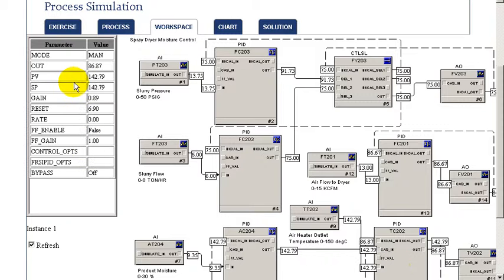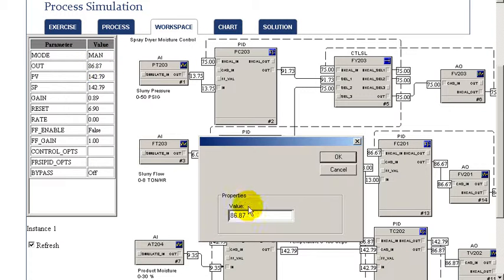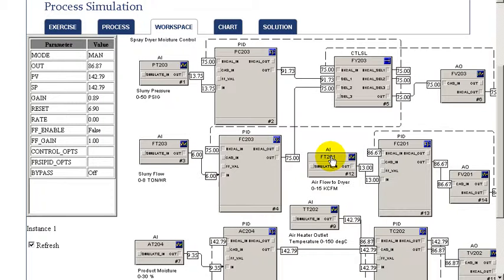As an exercise to demonstrate the benefit of automatic control of composition, we'll change the outlet temperature to try to guess what is required to bring our product moisture back up to target. In this case, we made a change, and as a result of that, we noticed that the composition is coming closer to target, but we guessed wrong, and therefore we didn't achieve the target value.